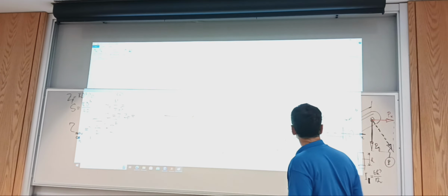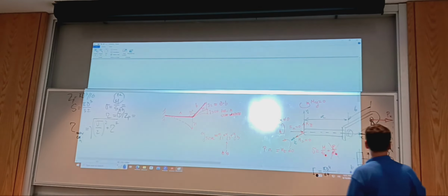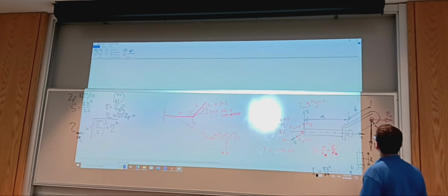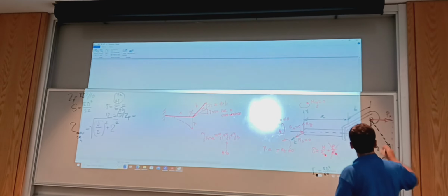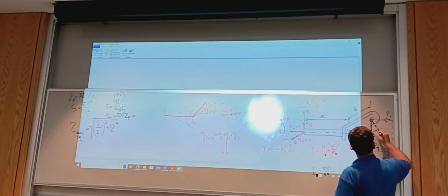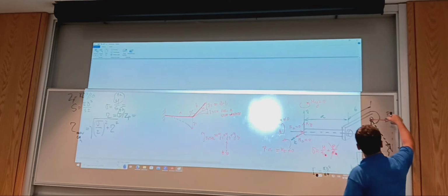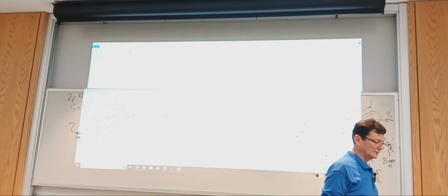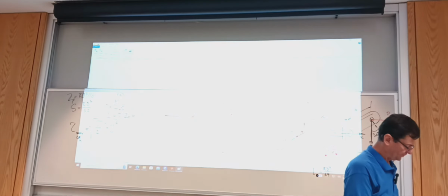Okay? And we can assume P is 1,000 newtons, like it was, and we can assume some angle. So we can take this at 30 degrees, in which case Px and Py can be calculated. Let me see, do I have the calculator? Yes, I do.